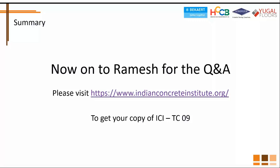So yes, you can avoid a separate layer of sub-base, but you need a lot of experience and care. It cannot be done in every situation. It definitely cannot be done for sandy soils. So you need a lot of expertise to be able to do this. The short answer is yes.